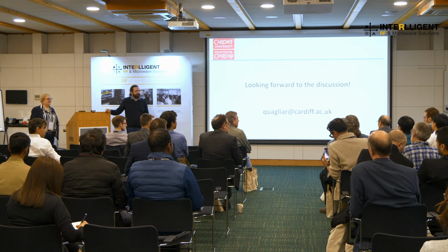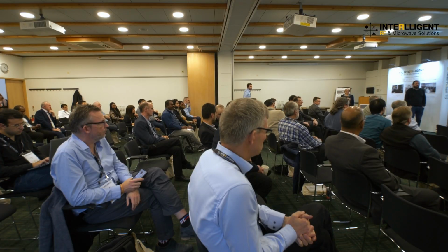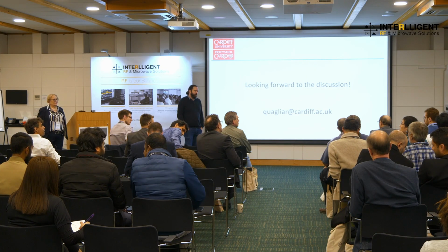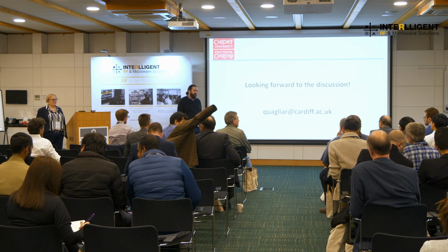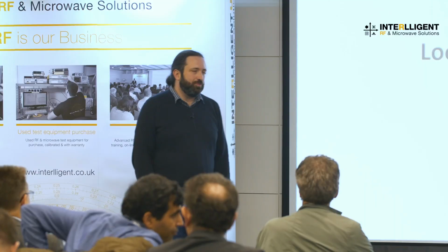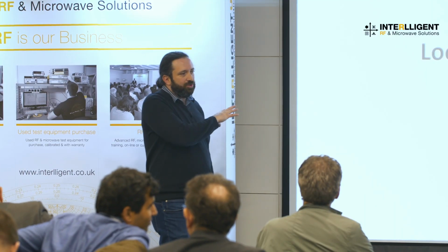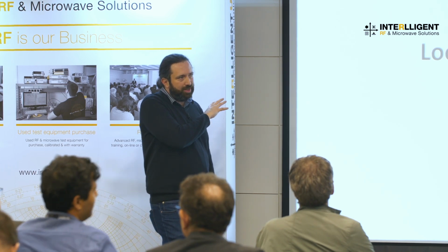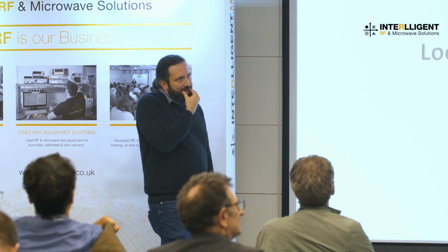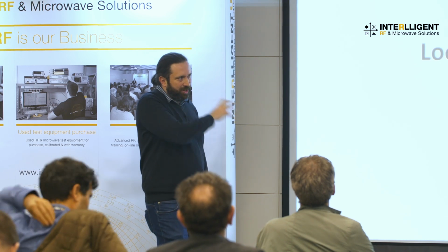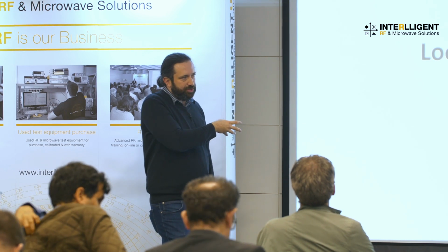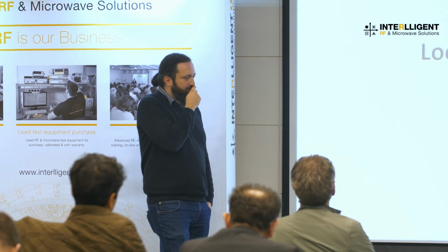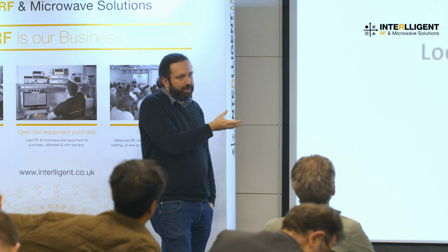A very quick one. Since you actually have a feedback from output to input, how did you manage to control the oscillation? Oh, well, that's another good point. Of course, behind all this, you have to keep an eye on the stability of the thing. And in the Doherty, because we are trying to get as much as we can out of the transistors, you just don't want to do unconditional stability, because you lose too much gain.